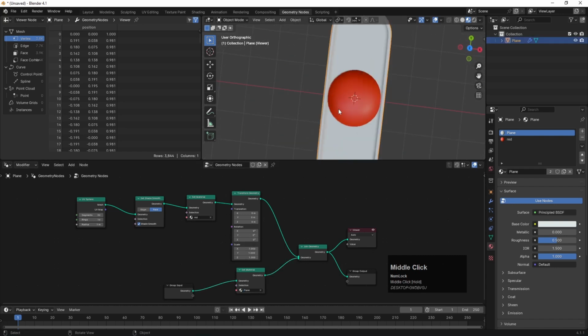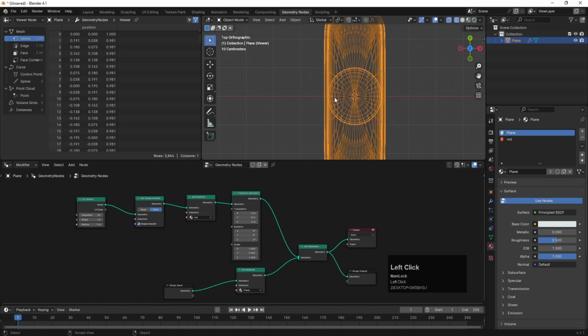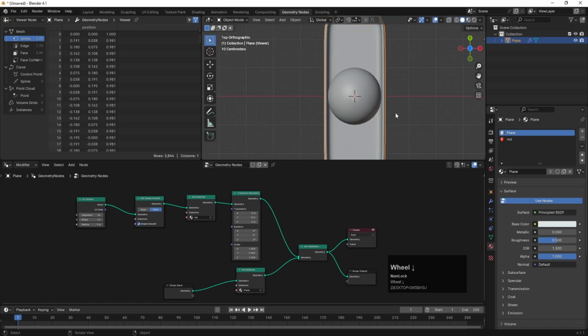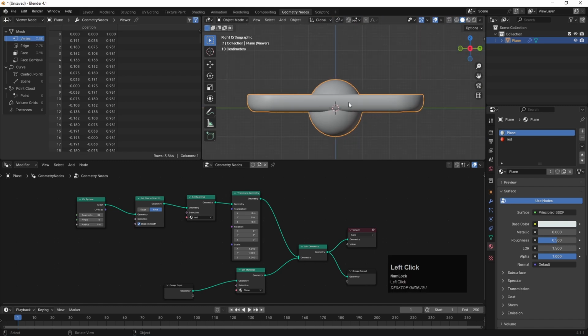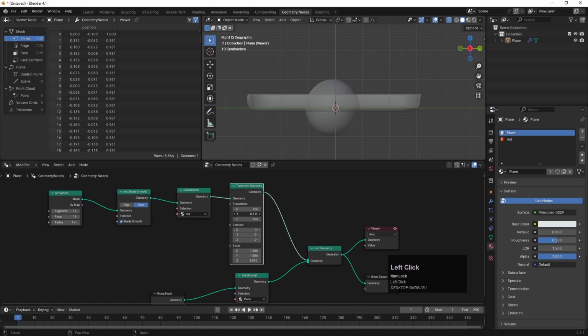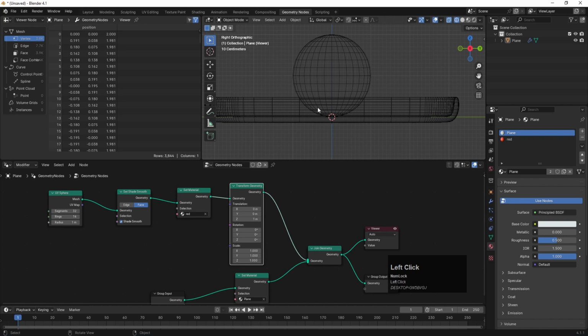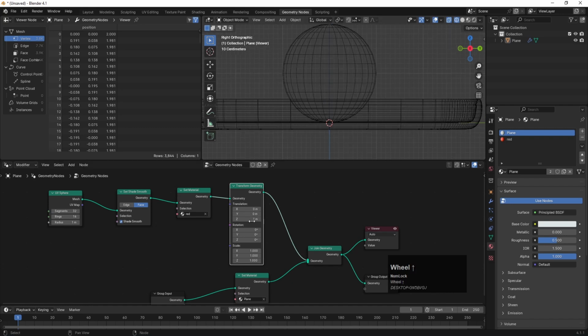First of all, I'll go to the top view, press Z and choose wireframe mode, and we have this perfectly aligned. Okay, then go to the front view, and now I need to bring this over here. So hold Alt Z, press Z and choose solid view. Okay, now let's select this transform, and now let's change the Z axis of this somewhere around over here. Okay, you can press Z and choose wireframe mode to see whether it's proper or not.